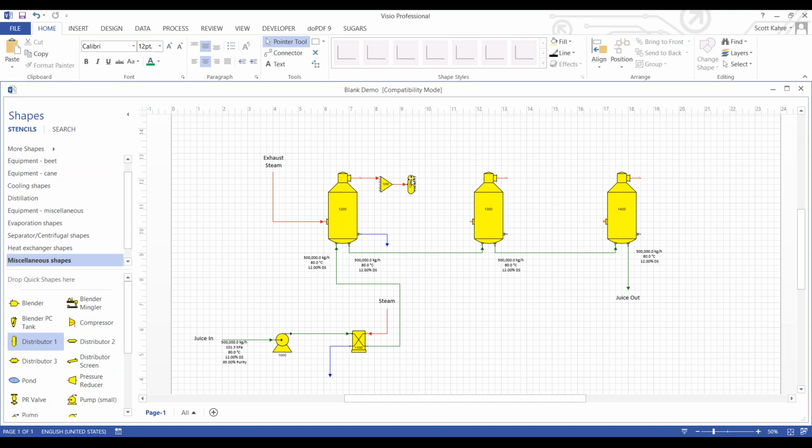So if we have a pan or a heat exchanger or some other steam user that uses first vapor, we can use this distributor to supply that vapor to that other user. It's always good practice to put both a receiver and a distributor station in the vapor line between each evaporator effect. That way, no matter what you need to connect to it, you have the ability to do that.